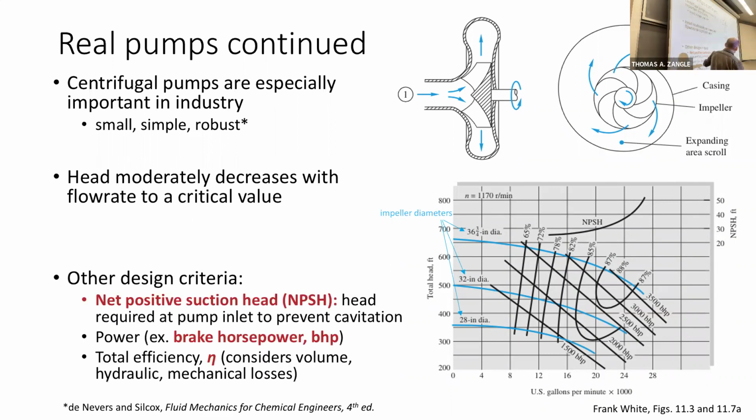Going into the details of specifying pumps based on one of these charts is going to be beyond the scope of what we're going to cover in this course. I just want you to be familiar with the idea that it's not all just about specifying the head that's provided by the pump. In actuality, specifying a pump goes a little bit beyond just that. There are some other design criteria, because you have to account for the fact that as you increase the flow rate that you are requiring of the pump, you are going to be decreasing the amount of pressure that the pump can provide.